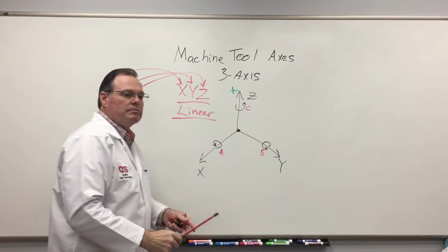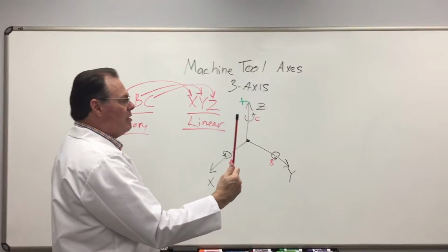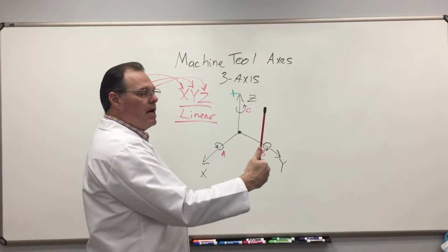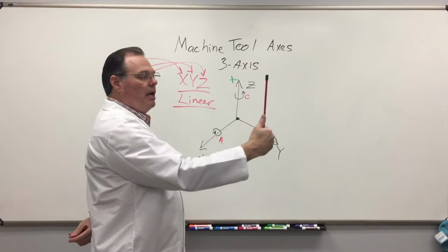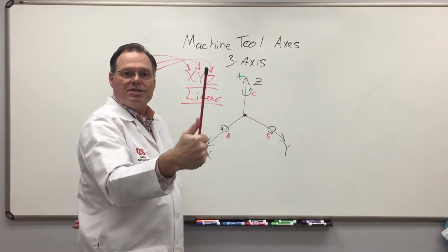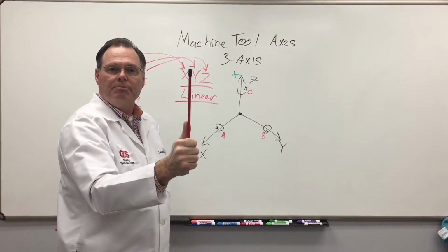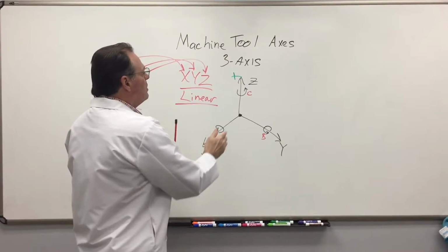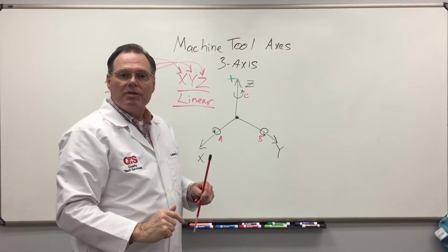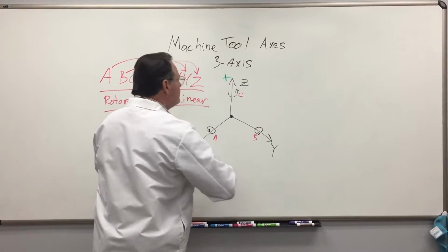and if I take my little linear axis, if I call this Z-axis, and I wrap my hand around here with the positive direction as my thumb is going, and I rotate this way with my fingers, that will be plus. The rotational axis will be in the plus direction here. So this direction, or counterclockwise, would be in the plus direction.